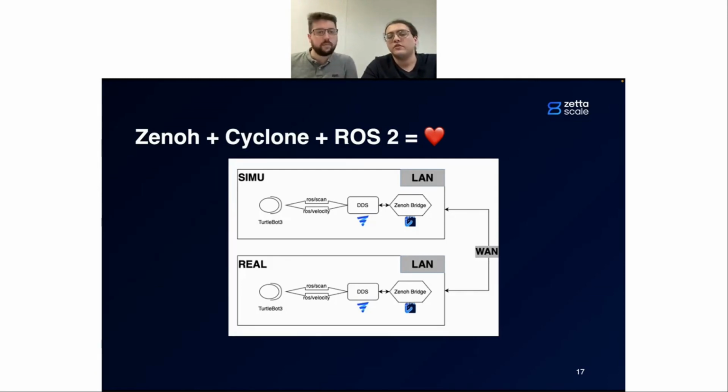Local area networks. And so the normal scenario you consider with ROS, right, is you'd have Gazebo running as your simulator, and then on that same LAN you would have your real robot hooked up potentially, and then you can see the robot interacting and you can teleoperate via that. But in this instance, and like you had mentioned with the Indy Autonomous Challenge, that would be... No, that's here. Oh, sorry. That's here. So in that instance, they used the Zenoh bridge to punch out from the simulation, and I think the cars are running on a special network there. And so then you're able to punch out from the simulation that the team was using to view and interact, and then punch into the actual real network running on the car, traveling at hundreds of kilometers an hour autonomously.